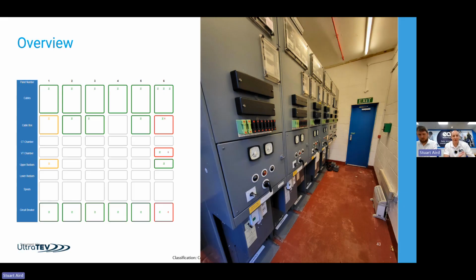So there are two totally independent tests, so we should always be doing a transient earth voltage test and an ultrasonic test to make sure that we can cover both types of partial discharge, both internal and just surface and your corona type discharges. So this layout here is out of the software, so we can see each of these symbols. They indicate a TEV measurement, and they're all green. A couple of ambers at the end, probably a battery charger at the end of the substation.